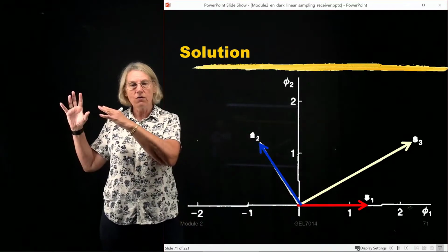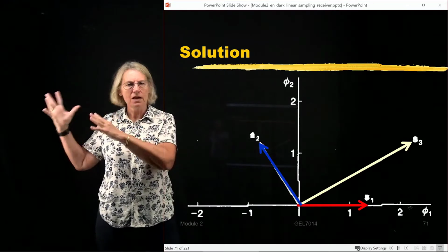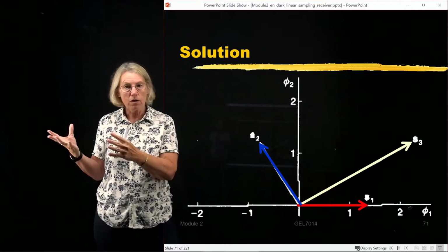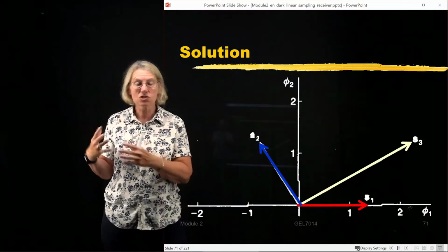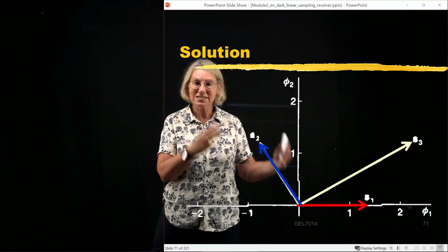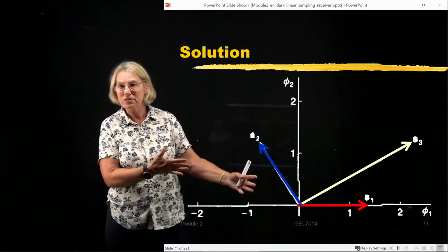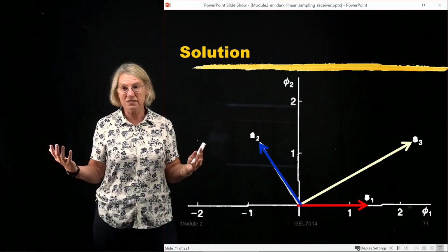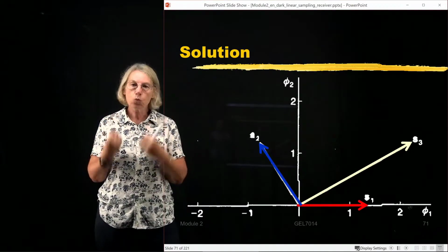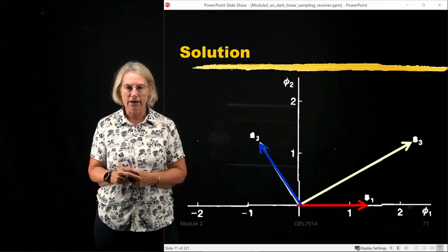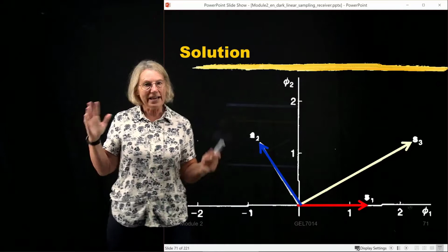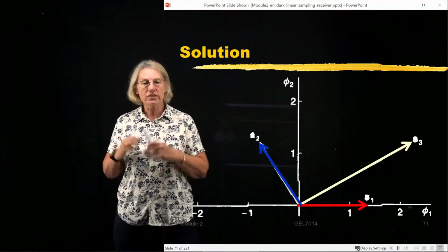And so we're able to take choices for waveforms which may appear to be extremely different approaches, but we'll see that when we look at their equivalent in signal space, their signal space representation is actually identical, which means that they're going to have the same performance, the same characteristics. So it's a great tool to help us understand what's going on with our modulation choices, our choices of waveform.